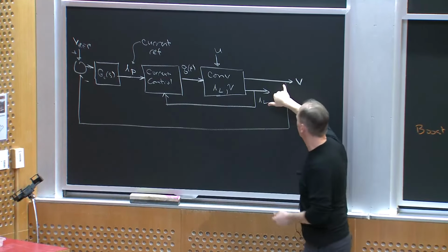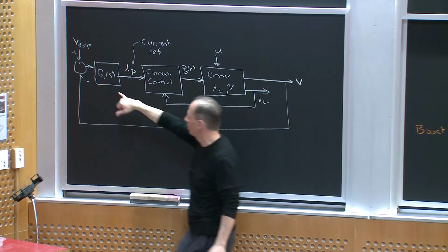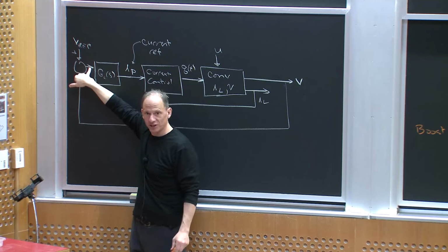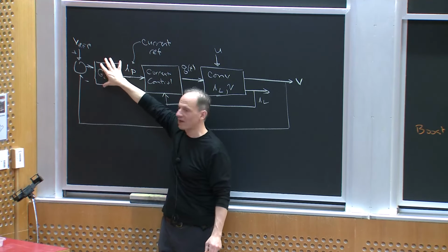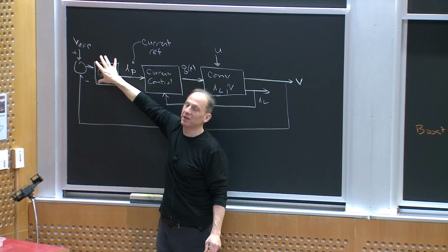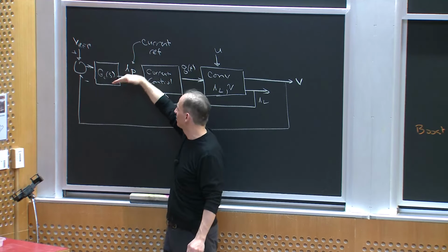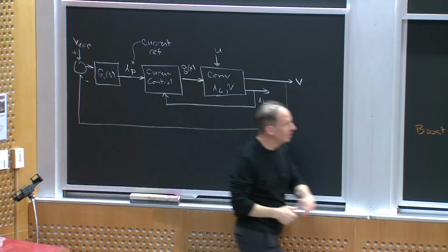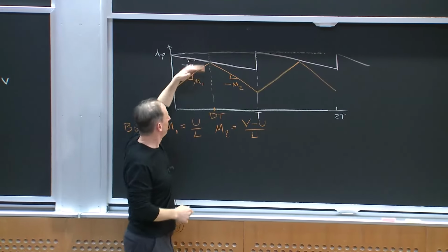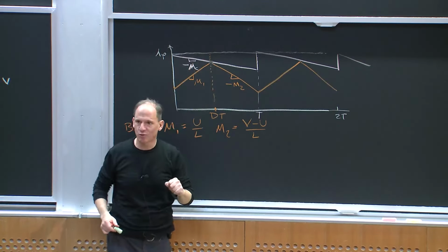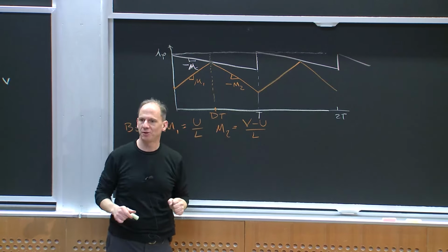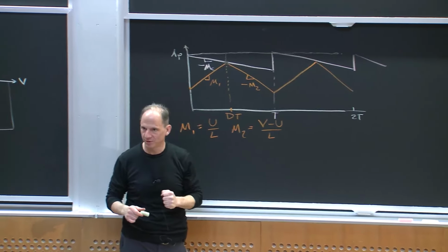If the load voltage is too low, meaning below the reference, the error voltage gets bigger. This outer loop compensator amplifies that, maybe it integrates the error, and will make the peak command get bigger. If this peak command moves up, so will the switching time, and then the inductor will have more current, and eventually the inductor will feed the output and bring the output voltage up, right?